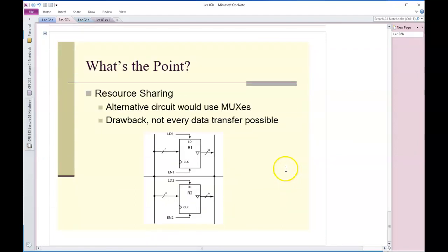Okay, so the point here, once again, is device sharing, and this is a circuit for that. I know there are more in-depth examples in the book with two registers, but what can you do with two registers? If it was set up properly, that means I would need some muxes sitting in front of this thing, and I could actually swap the data in these two registers in one clock cycle. But it's not set up that way. This is set up as a tri-stated circuit.